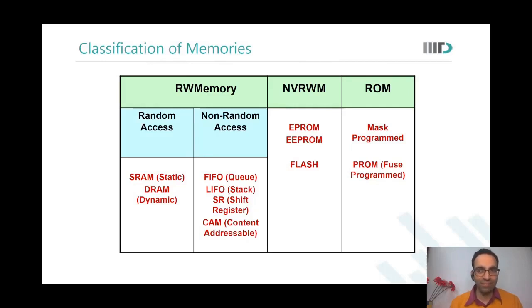Sir, can FIFO only divide the frequency or can it also multiply? Because Raghav said it will give the frequency in subdivision. But in the second case, when you showed, it required some higher frequency. So can we use the FIFO in the reverse order? FIFO cannot generate data. FIFO has a limited capacity. It can store only as many words as it has. If the other side needs more data, then how do we do it? We can't do it.